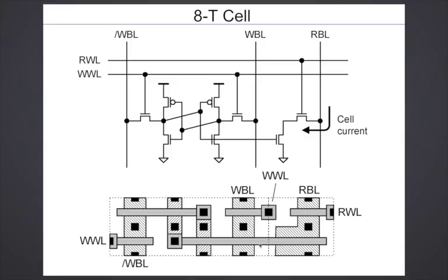Of course, you increase the word line length, but the word line is being driven by a simple inverter. You can make it a little more powerful to drive that extra load, extra wiring. And only one word line activates in any row, so that extra capacitance and power is not that significant. Now this is the buffer, the read buffer. So the internal node of the cell comes in and is connected to the pull down transistor here, and then this is the access transistor, and the read bit line goes vertically. Of course, you have two word lines, read word line and write word line. So all of this basically increases the area of the cell.